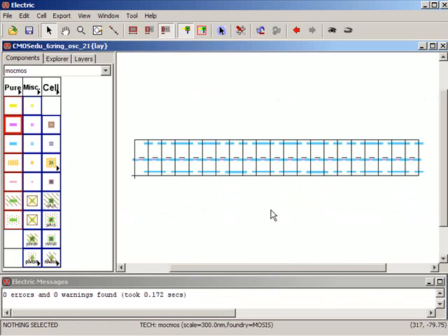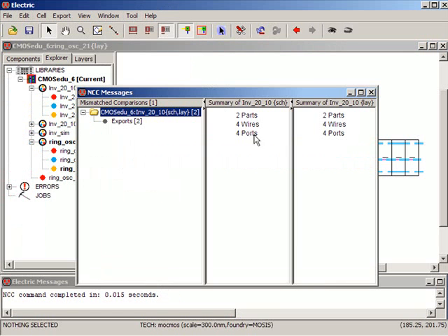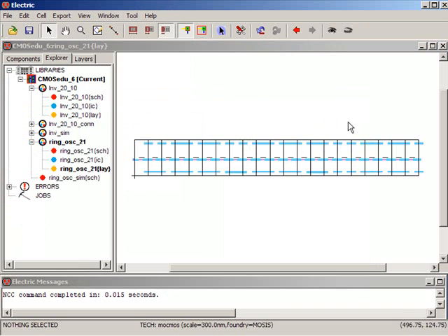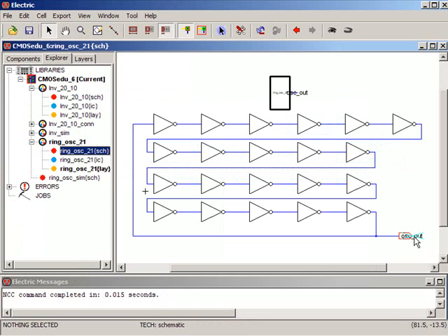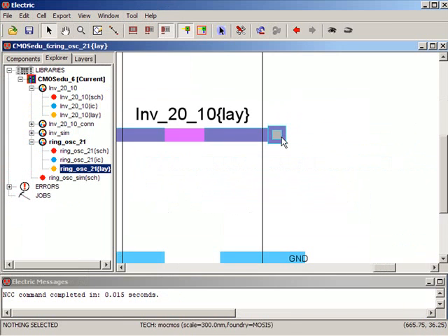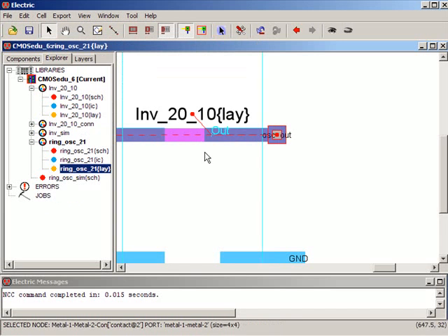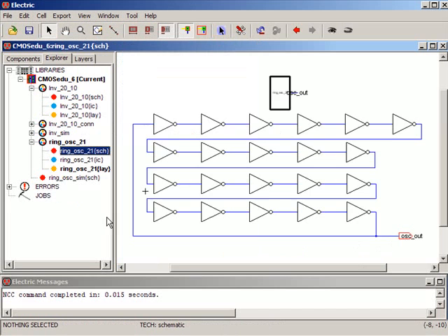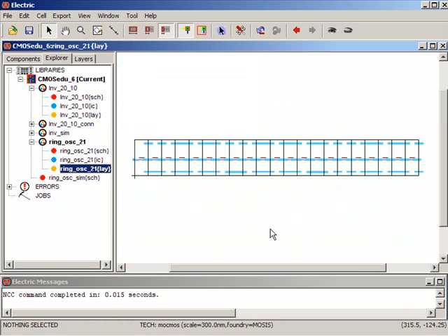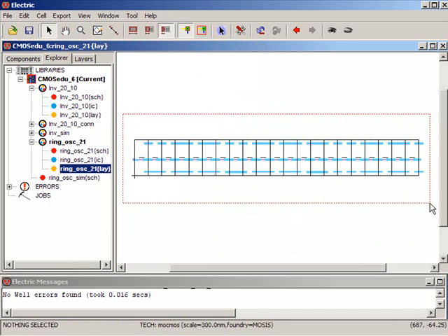All right. So let's export the output here. And what did I call that in the... let's do an LVS real quick. And there's our VDD and ground implied. Let's go back over here and look at the schematic, and I called that export oscillator out. Let's go back, zoom down here, and select that, Control E, oscillator out. And did I call it uppercase there or not? Nope. Okay. Fit. Let's do an F5 again. Let's check the wells. Let's go ahead and now look at the layout.